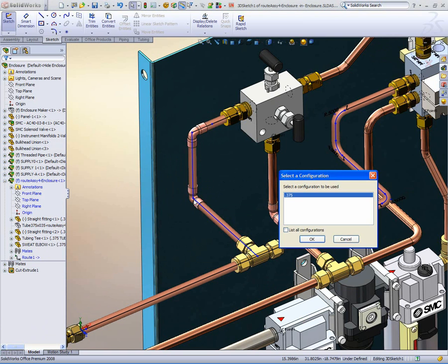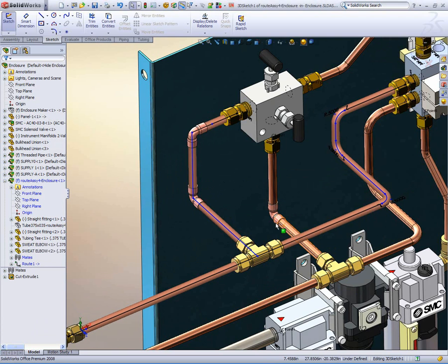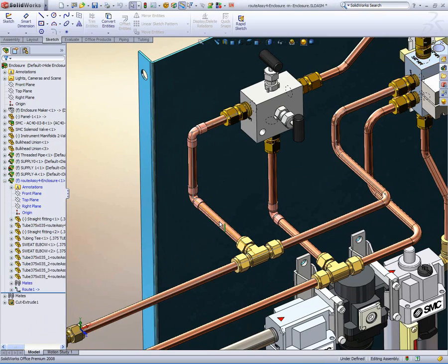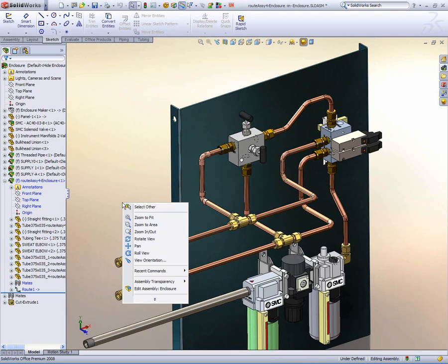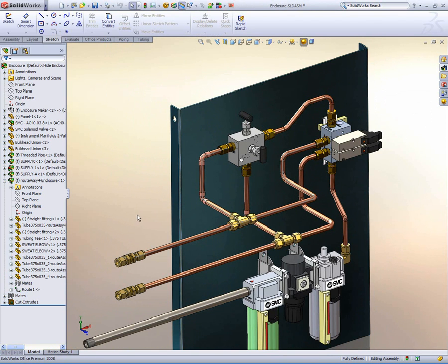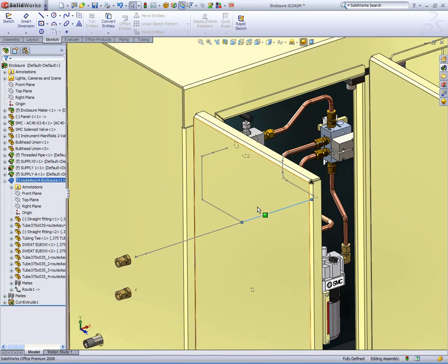One of the benefits of SolidWorks routing tools is that behind the scenes, SolidWorks is always trimming up the pipes to be the appropriate length for manufacture. So again, you can see as we did before, it's simply a matter of dragging and placing various fittings into our design and drawing some lines to connect those, and SolidWorks takes care of the rest of the routing of the pipe.